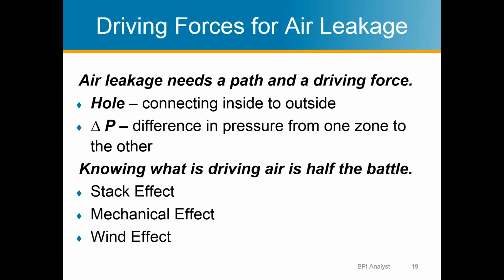However, if there's a hole, say the door is open in my office right now, but there's no pressure difference between my office and the hallway, so there's not necessarily air leakage through that door. So every air leak needs those two things. And then what's driving these air leaks is the stack effect, which we'll talk about in a minute.